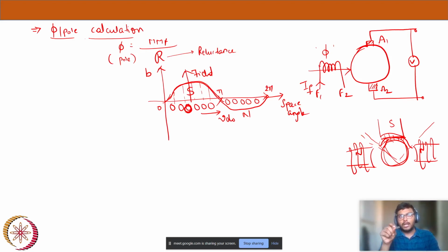It's not that we define it for motor; it's defined for generator, but the principles apply in that condition. When we talk about a generator, we talk about field first, velocity first, and voltage later. That's why we use the right hand rule. When it comes to a motor, we are already giving supply directly to it, so we don't talk about the right hand rule. In the left hand rule, we will talk about the direction of force. We will come to that point later.